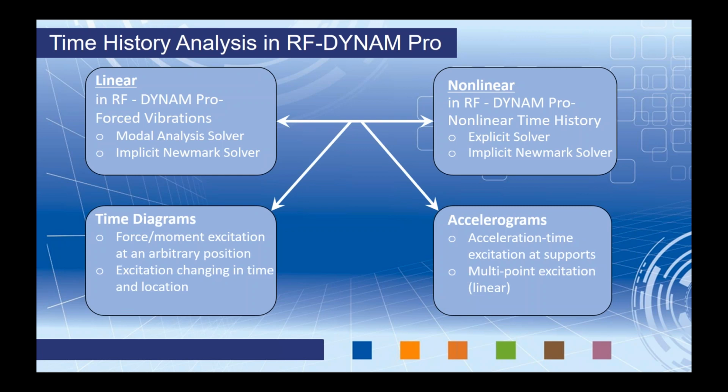Now, for both of these solvers, whether linear or nonlinear, we have two different options. We have either time diagrams or accelerograms. With time diagrams, this is a force or moment excitation at an arbitrary position. We define our time diagrams with tabulated values, which can be imported directly from Microsoft Excel, for example. It can be a periodic function, or it can be a direct input of a function within the edit field.